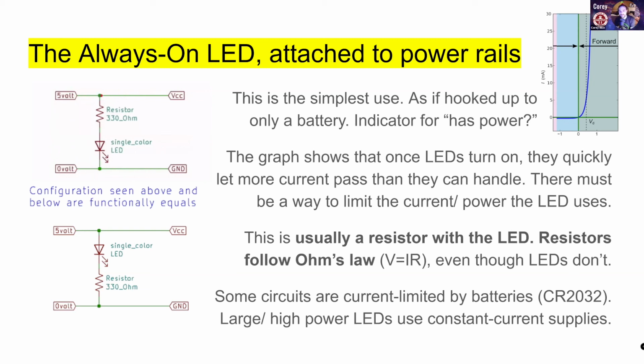Ohm's law applies to things that have a fixed resistance, whereas an LED doesn't. It has P and N junctions that switch on or off based on the direction of the current flow, and it's more subtle than that. But you can think of them as something that turns on if the current goes in the right direction and turns off if it goes in the wrong direction. Turning on or off doesn't really follow the idea of added resistance and restricting current flow. So because they've got that weird behavior,